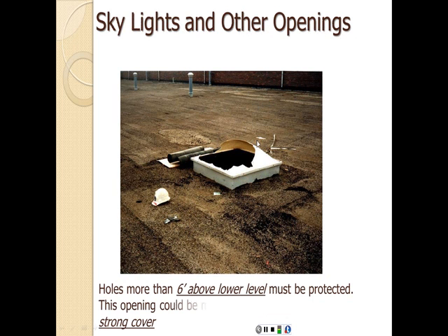Skylights and other openings in roofs, again, obviously that's a falling hazard. So holes more than 6 feet above the lower level must be protected. This opening could be made safe by using a guardrail or a stronger cover to protect from falling.